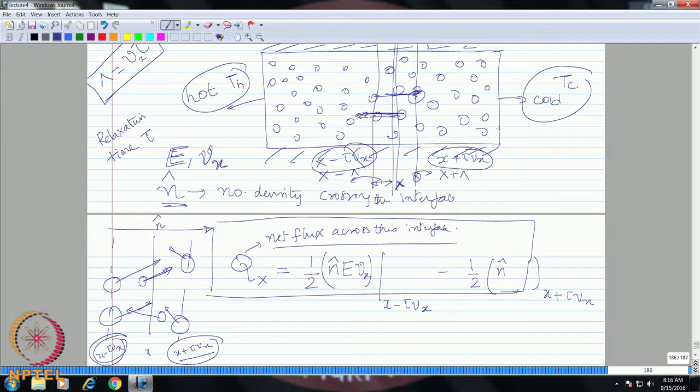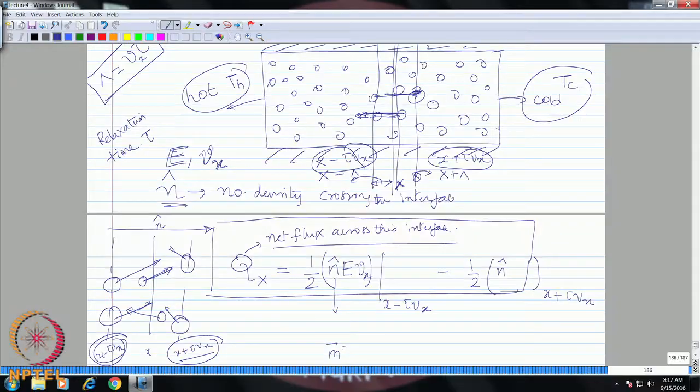What is the unit of energy flux? Joule per meter square. So, therefore, this is something per meter cube. Okay. So, a number of molecules times the energy per molecule. So, this is joule per meter cube into meters per second. This is watt per meter square, right. So, if you look at your Fourier's heat conduction law, Q is equal to minus K dT by dx.